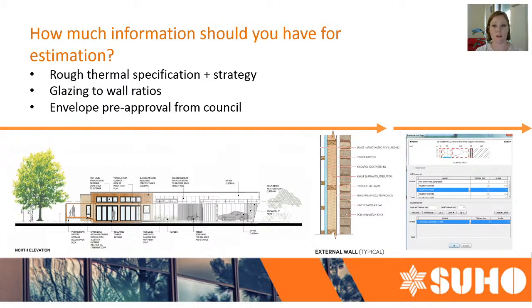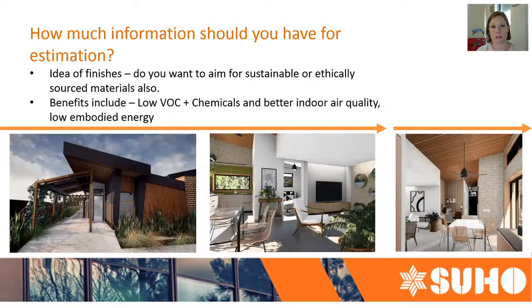So First Rate 5, which is where this snippet comes from, is very good because we can really analyse that from the word go. Different types of insulation as well. I mentioned rock wool versus a healthy earth wall. They can perform a little bit differently in the software, same as polystyrenes and so forth. So it's a really good idea to have a very rough specification of what it is that you're wanting to get out of these materials in the design.